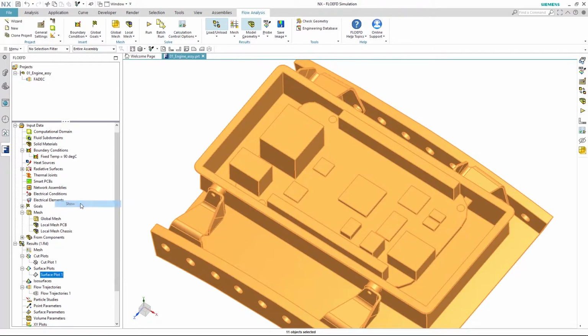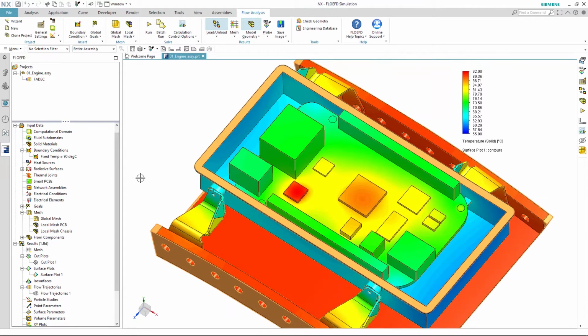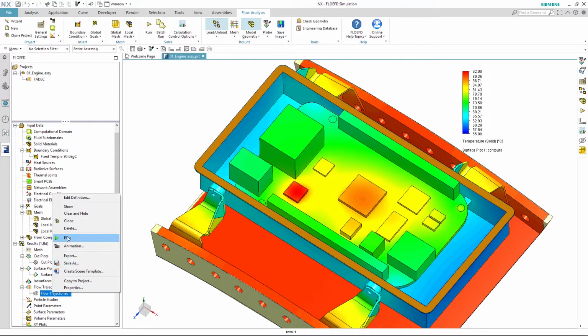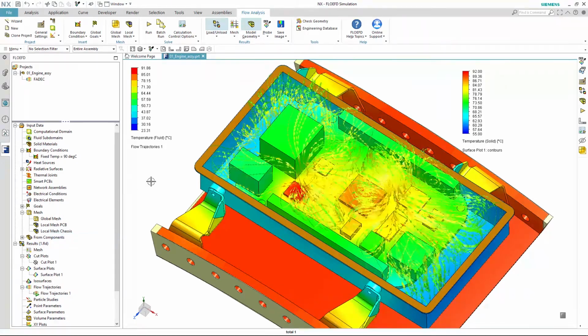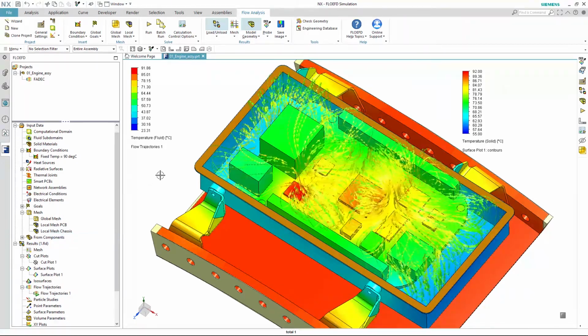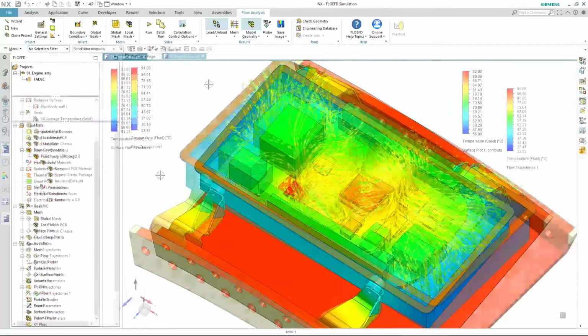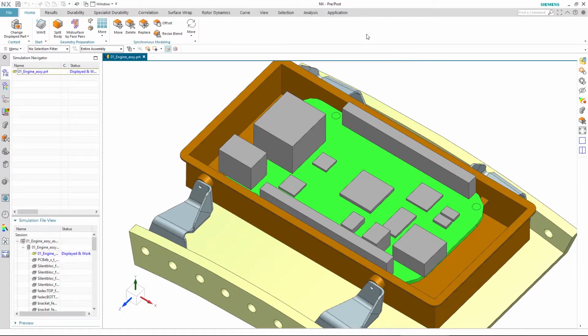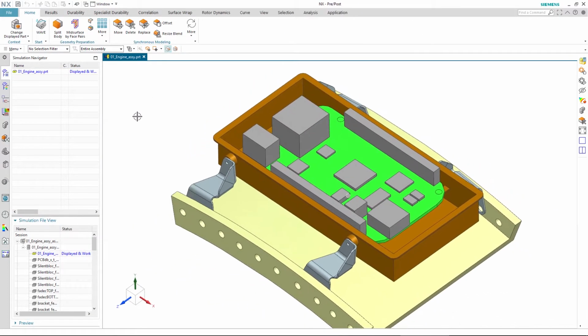A full 3D CFD thermal simulation in SimCenter FloEFD predicts operating component temperatures as well as PCB temperatures. Natural convection airflow distribution within the FADEC enclosure is also predicted. The FloEFD results are unloaded and the SimCenter 3D pre-post interface started directly on the same model geometry without leaving the Siemens NX session.